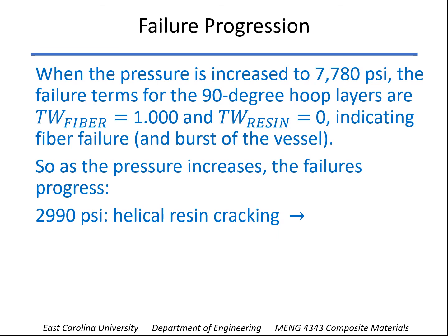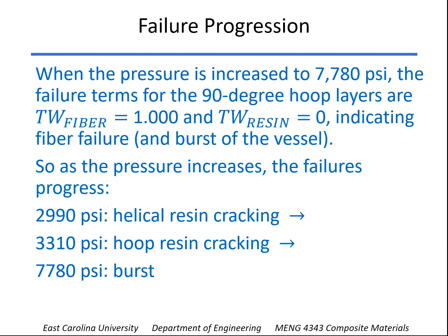When we get to about 3000 psi, we're going to have the helical resin cracking. A little bit above that, then the hoop layers start to crack. So that when you actually do a test with this, you'll see it's pretty noisy around that. Then it kind of gets quiet again because the resin's all cracked. And then, at a pressure even double that is when you finally get burst.